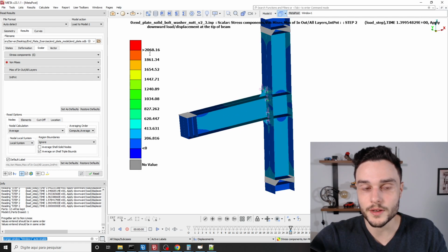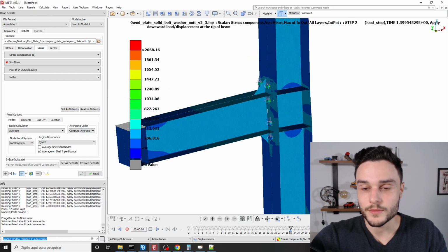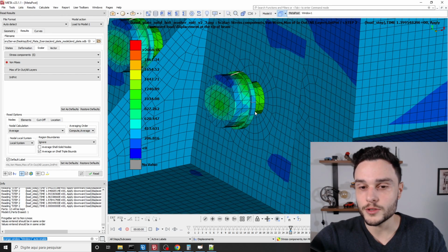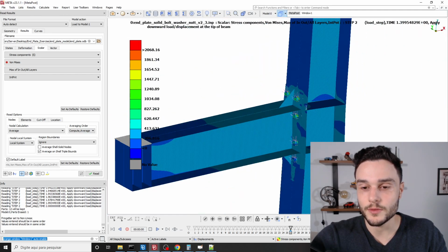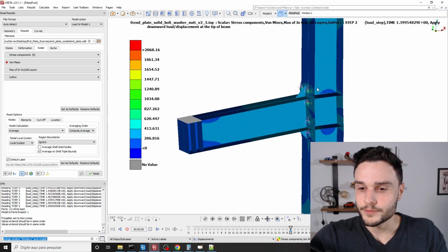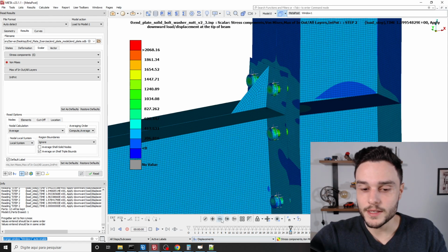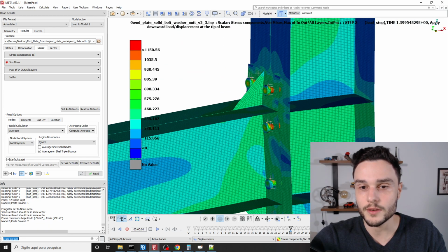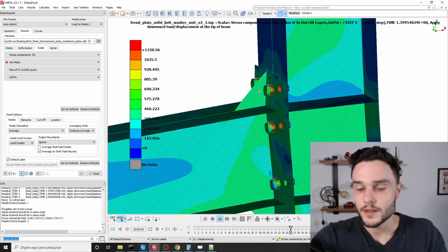And then it's showing here the stress. This large stress is probably in the nut or washer, because we didn't define plasticity for these modules. So this is not realistic. If we hide, let me use not function, select by property ID, select one washer, it's going to hide all washers and nuts.